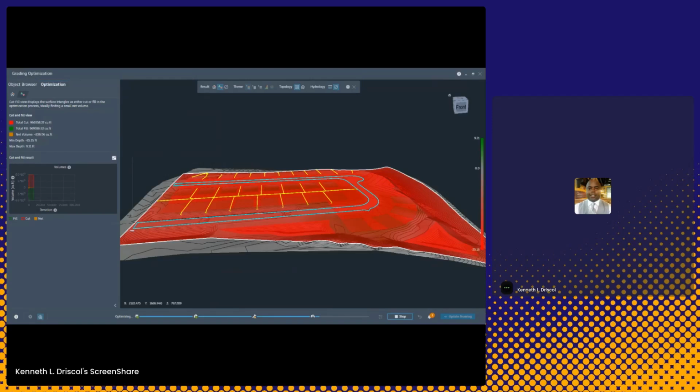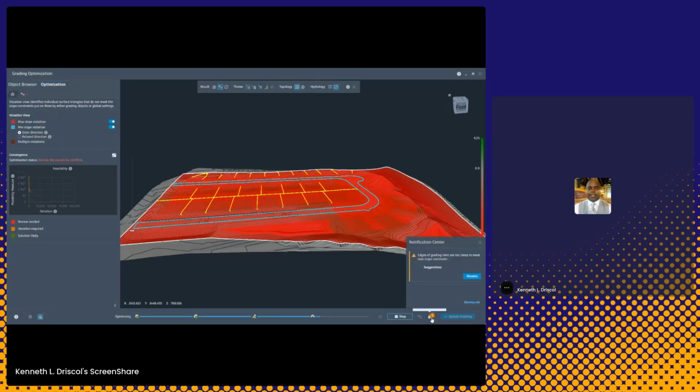offsetting grading lines, which is a polyline. Draw a polyline for my influence for my drainage arrows. Assign a zone for my grading. Rough grade for pads. Run a grading optimization until this feasibility shows me what's going on in terms of optimizing. And from that, I can make adjustments. And then it also makes recommendations about what's going on. Edge of grading limits are too steep.